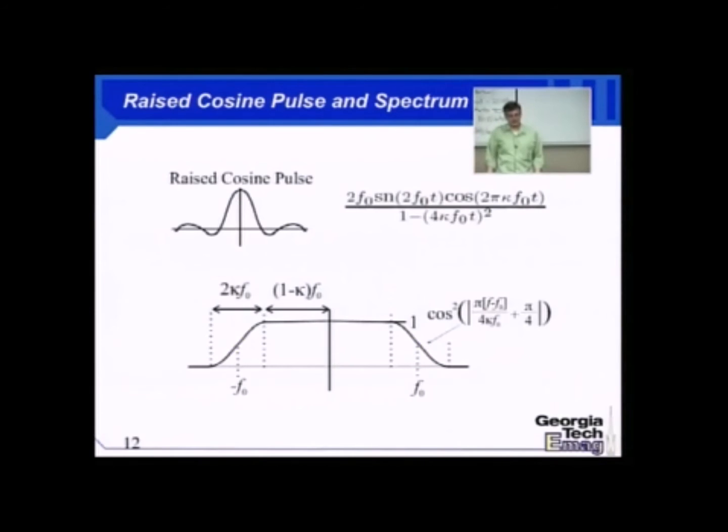You get this family of pulses that's just like the sinc function, crosses zero at even intervals. Therefore, it satisfies the Nyquist intersymbol interference criterion. And it turns out that kappa is really nice for adjusting the roll-off of your signal. By ramping up kappa, you get functions in the time domain that are more amenable to clipping. You can clip their support in the time domain, and they ring less in the frequency domain.